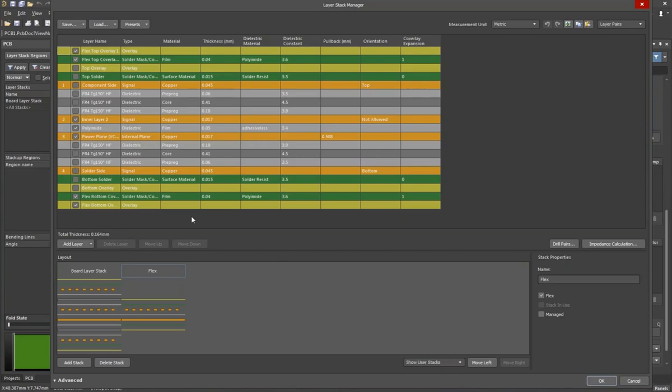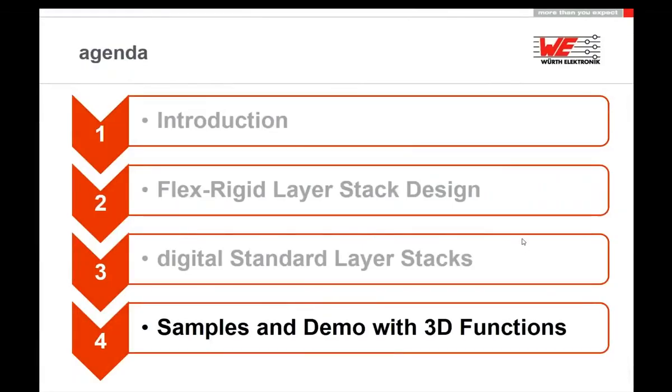So that only those 2 layers can be used later in Altium for the routing. All the other layers and dielectrics are not activated, only the cover layers are activated as well. Additionally, when you go to the right side of this advanced tab, you see the flexible stack-up. You need to activate that this is really a flexible stack-up. So you need to activate this button here.